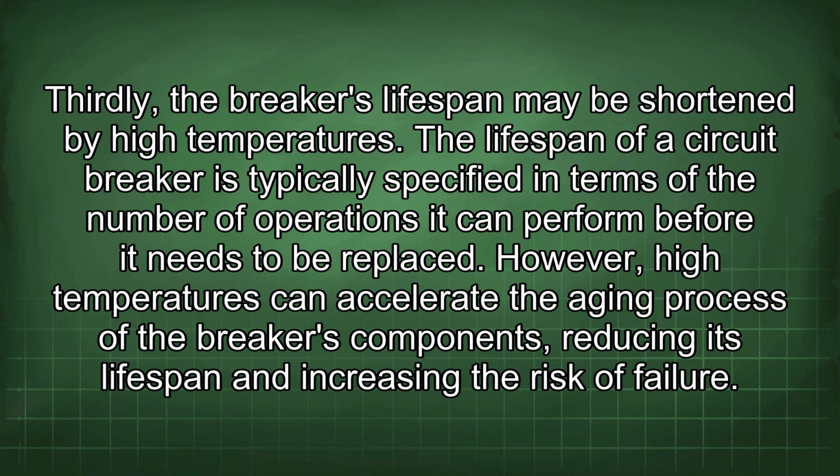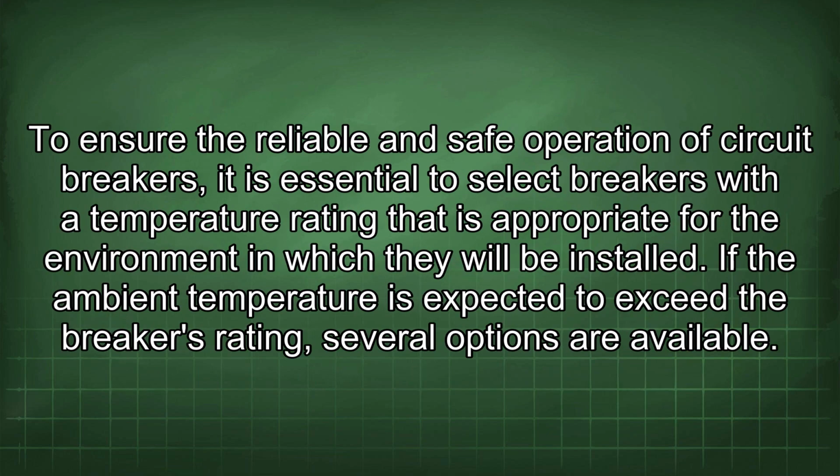Thirdly, the breaker's lifespan may be shortened by high temperatures. The lifespan of a circuit breaker is typically specified in terms of the number of operations it can perform before it needs to be replaced. However, high temperatures can accelerate the aging process of the breaker's components, reducing its lifespan and increasing the risk of failure. To ensure the reliable and safe operation of circuit breakers, it is essential to select breakers with a temperature rating that is appropriate for the environment in which they will be installed.